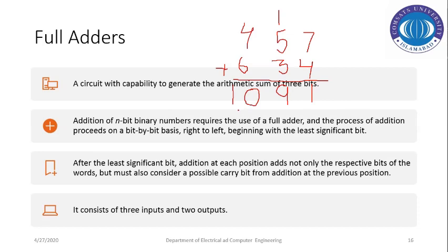These concepts are implemented as they are on binary data as well. So we can see that at any placement there is a possibility that a carry can be added, whether it's a decimal number, a binary number, or whatever the numbering system is. There is a chance that at any placement the carry generated by the previous addition can also be added. A half adder circuit does not have the capability to add the carry in. So we're going to switch to the full adder circuits.